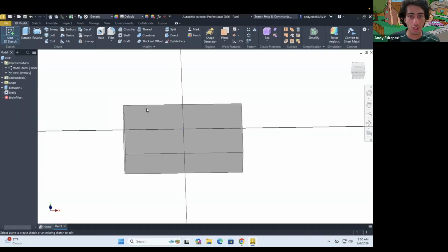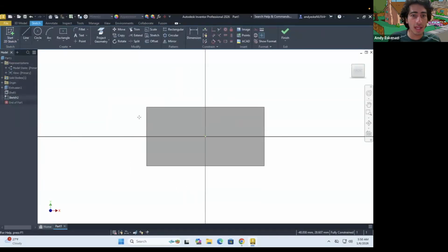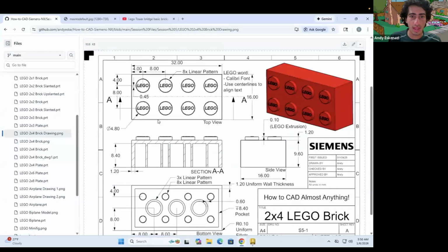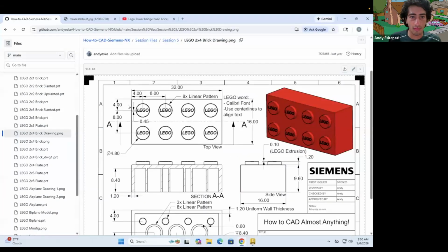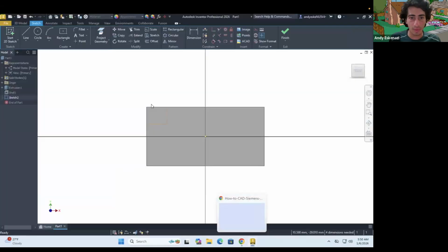We go here to sketch, and then we are gonna draw 2 lines. Let's go like that. I'm gonna make these 2 construction lines. And we are told that that little cylinder is at 4 and 4 from that edge. So I'm gonna go here to D, we're gonna make that 4, and if I find the other one, we're gonna make that 4. Now you see everything moved because I need to constrain that to be on the edge. So let's do that there.